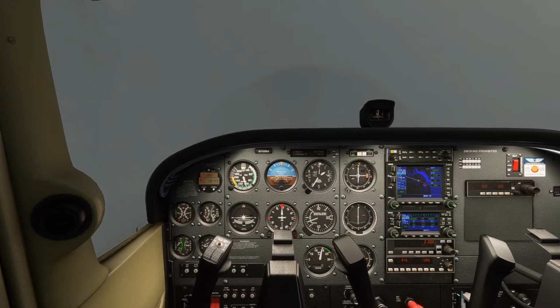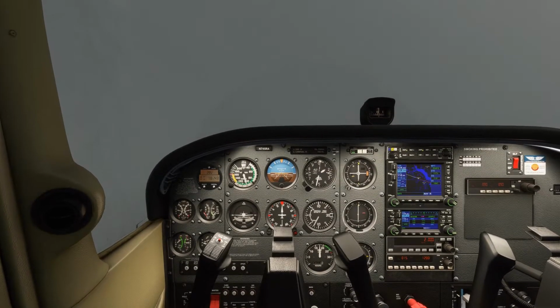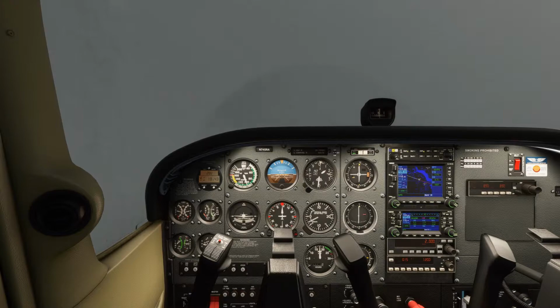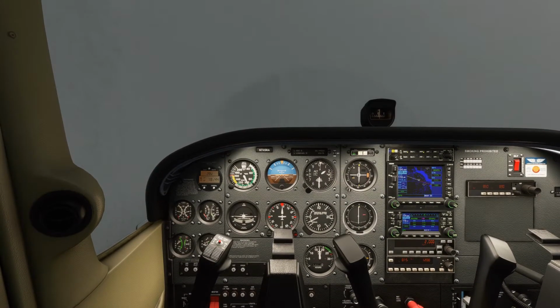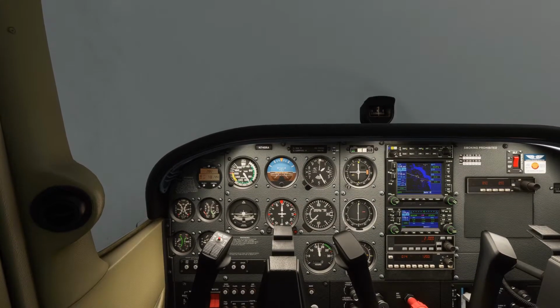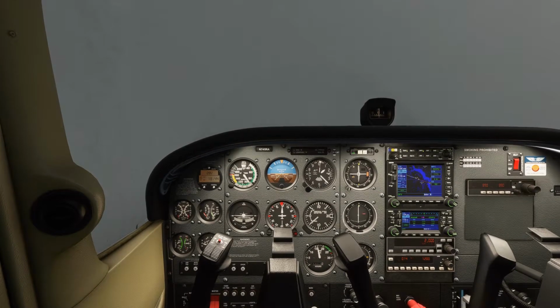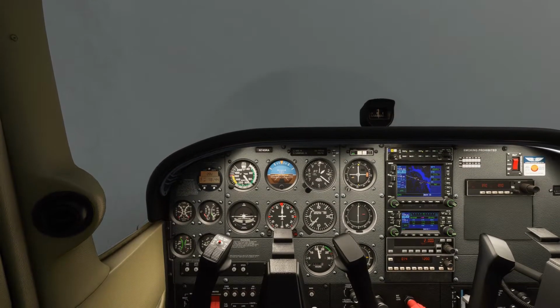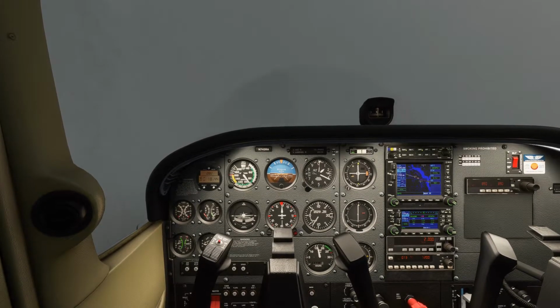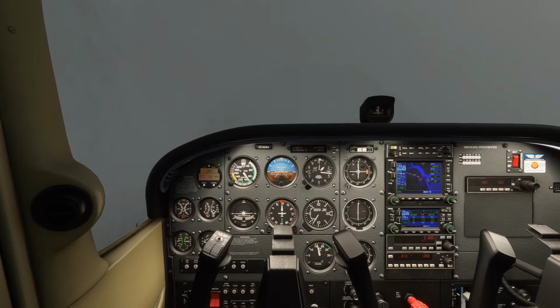So we're going to set 1700 to 1800 RPM, flaps 10, and then just pitch just below the horizon there. Should establish around about 400 feet per minute rate of descent. Maybe a little bit less power, seeing as the speed's taking a little while to come back. Now remember, there's no vertical guidance on this, so you're just making sure that your rate of descent is sensible and that you're meeting the altitude restrictions as you come down the approach.